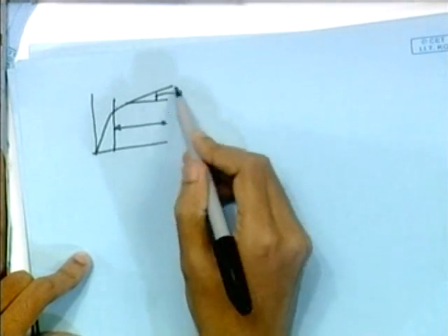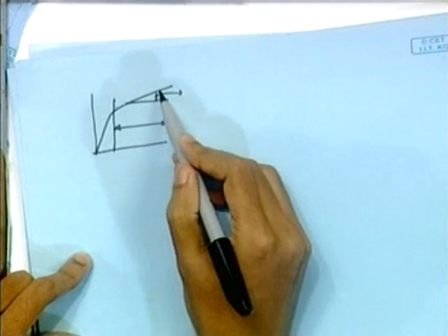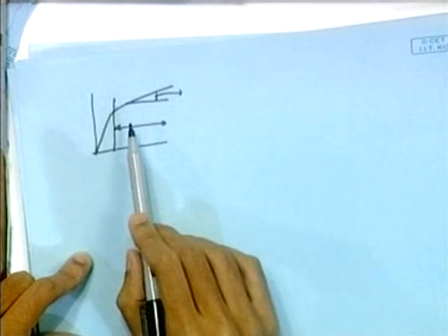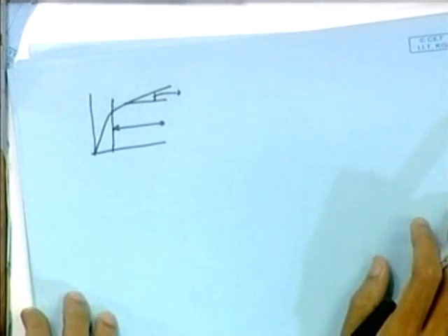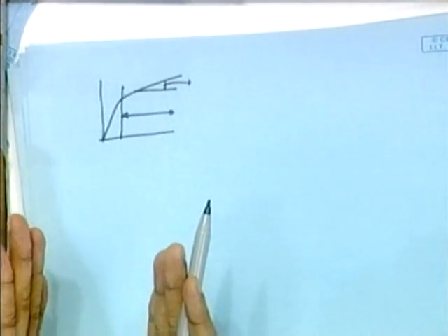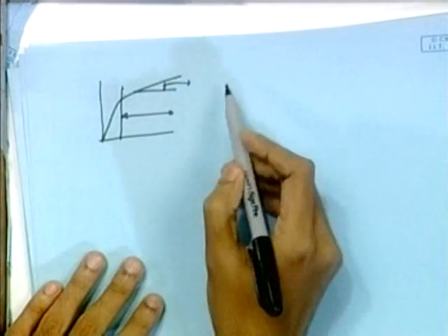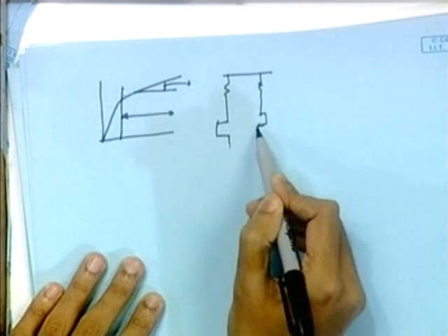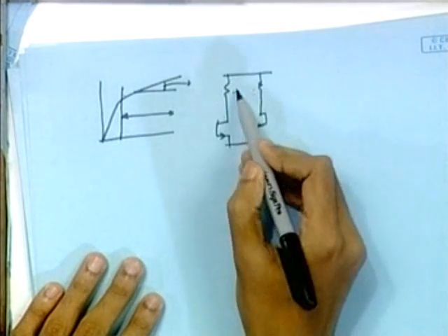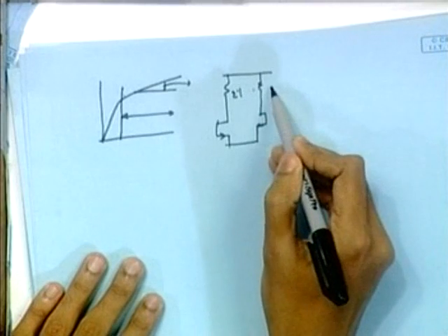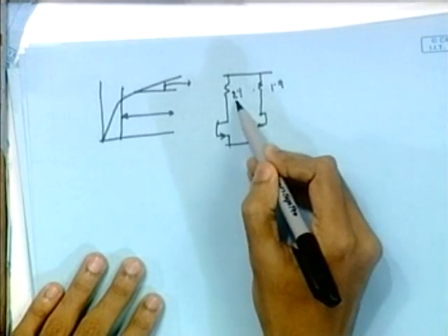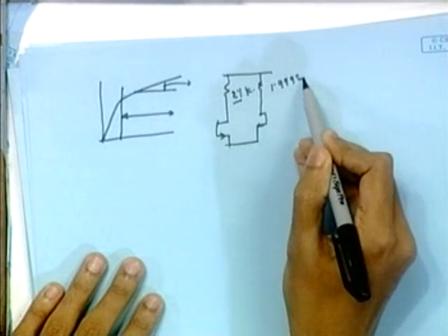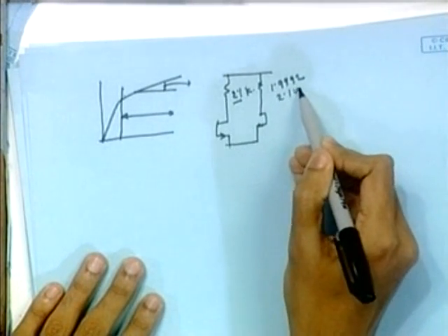Okay. So there are some effects of this finite resistance, and also there will be some mismatch between the branches. The resistance and transistors cannot be perfectly symmetric or perfectly matched to each other. This is true. Suppose this is 2 kilo ohm, it might be 1.992 or maybe 2.1001.